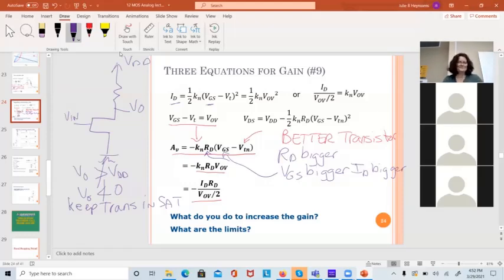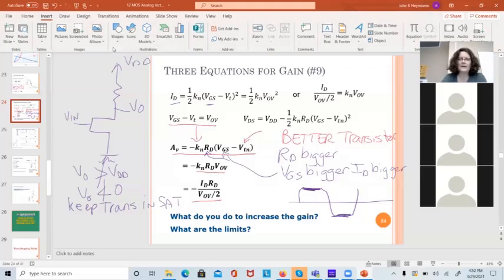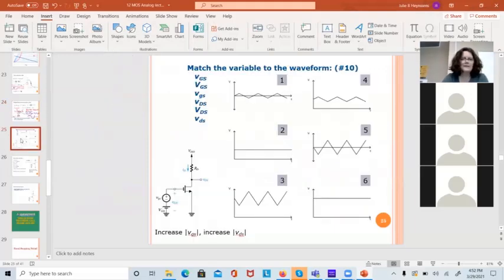It's something you've probably seen in the 188 lab. You put an AC signal into an op amp and you're expecting an AC signal out, and what you get is something that looks more like this, with these flat tops in it. That is your amplifier going into saturation. It's hit the maximum DC value that it can put out.